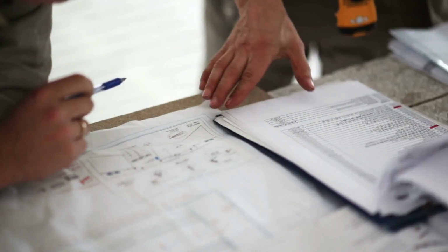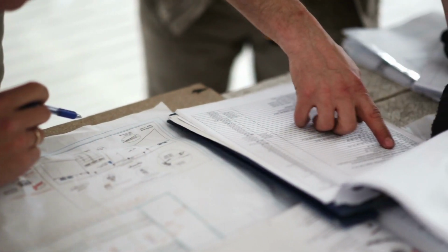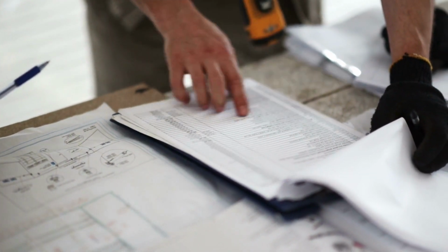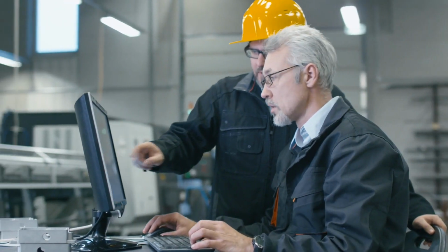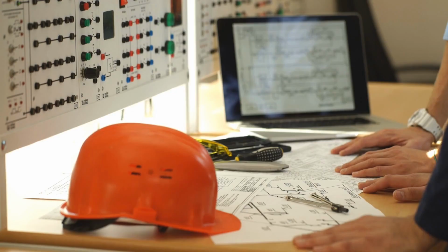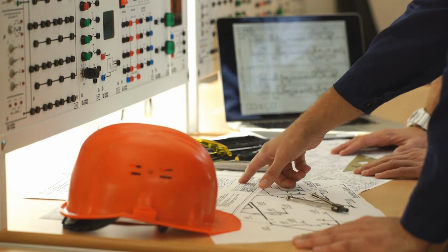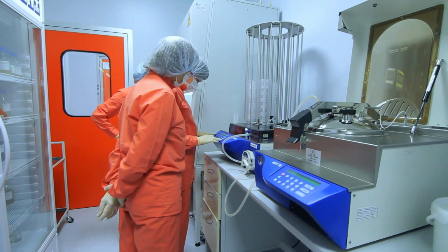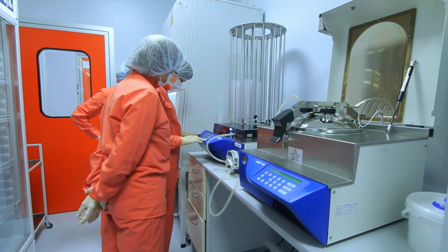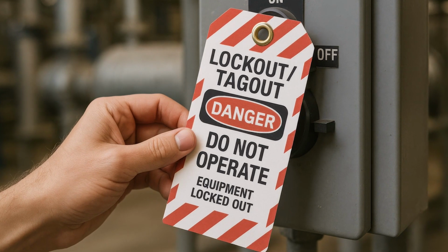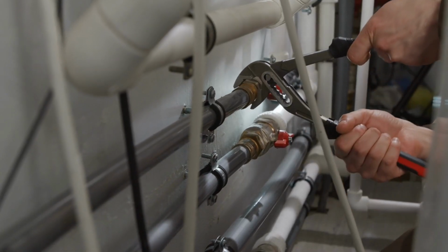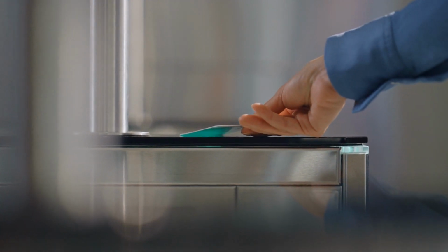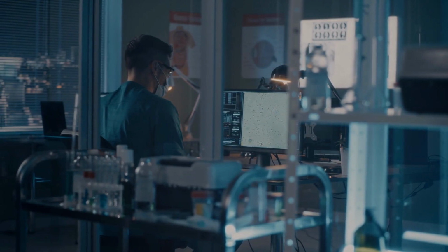Operating procedures must be kept up to date to reflect changes in process chemicals, technology, equipment, and facilities. These procedures need to be accessible to employees who work in or maintain the process so that they can review the most current practices. And every year, the employer is required to certify that the operating procedures are current and accurate. The employer must also develop and implement safe work practices covering the control of hazards in a variety of circumstances, such as during lockout/tagout, confined space entry, opening process equipment or piping, and entrance into a facility by maintenance, contractor, laboratory, or other support personnel.